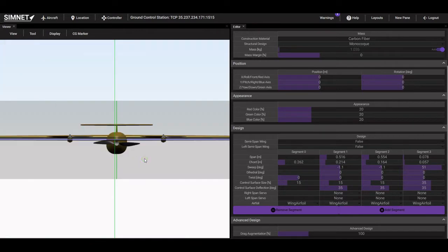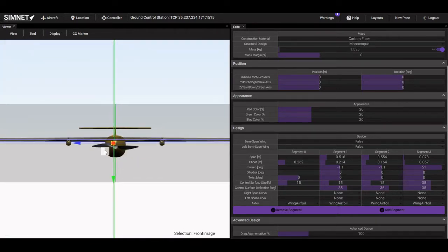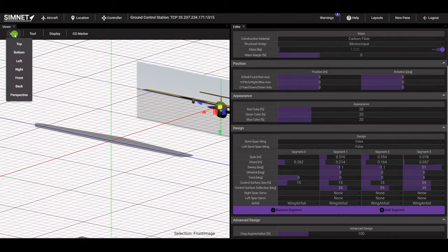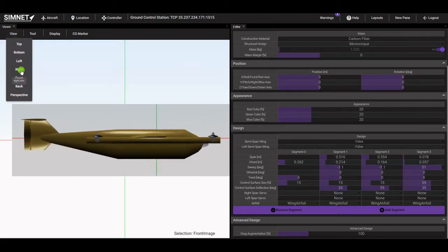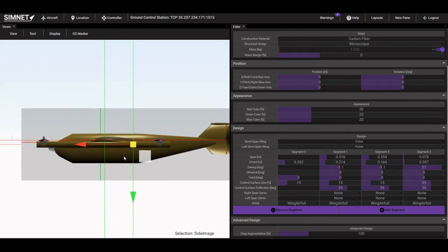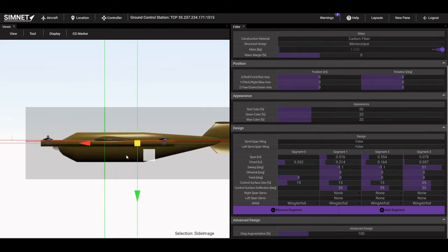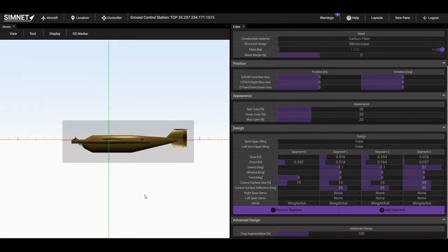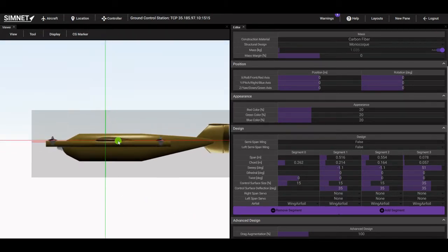Now that the main wing is mostly modeled, we can use it to adjust the positioning of the front and side reference images. If the wing has dihedral, use the front view to adjust the dihedral angle of each segment. You can set the wing incidence angle by rotating the wing around the x-axis using the rotation table. Let's set an incidence angle of 1.5 degrees.